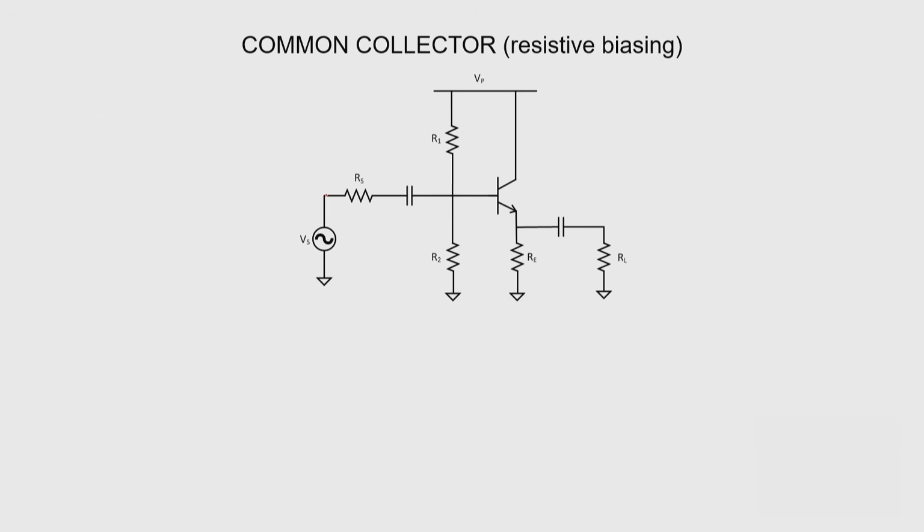We have an AC signal entering the amplifier. We might have a little bit of attenuation at this point. That signal reaches the base of our transistor, and the signal then reaches the emitter of the transistor and makes it across the capacitor to our load. That's if everything is going well. This is what we want. If this is what we have, then this amplifier is called Class A.